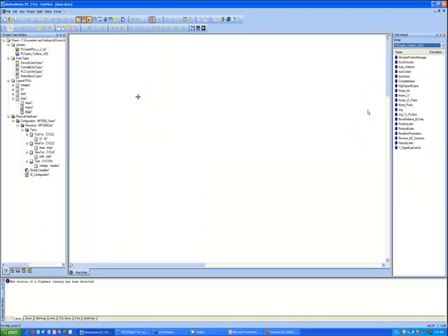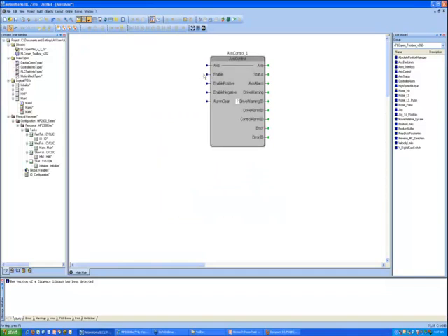You're going to see that we're going to have some typical problems come up. If I just try to compile this, I get a lot of errors, and that would be expected based on the sequence of operations I just did. There are a lot of duplicate names of data types. That is because the toolbox itself contains a copy of two of these data type files that are also available in a new project template. The toolbox needs those data types because it contains many of the PLC Open function blocks, and so it kind of serves as a basis for the PLC Open firmware library itself.